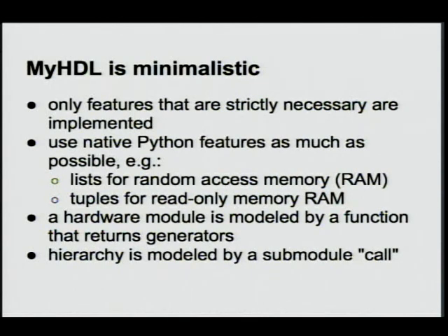These have a similar semantic meaning. Furthermore, for a hardware module itself, there's nothing special in MyHDL. You just use a normal function. A normal function is used to describe a hardware module. The only special thing is that it creates generators and that it returns them. That is the way that hardware is described.